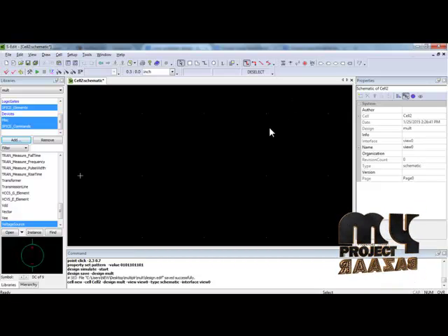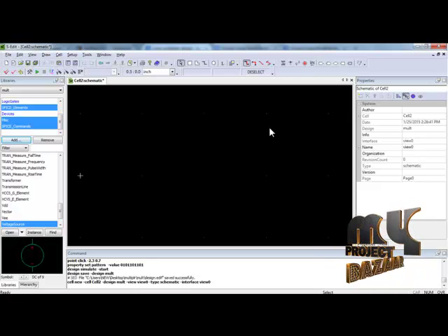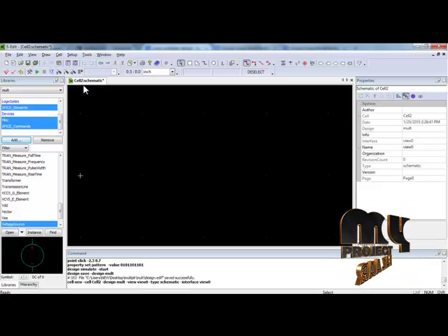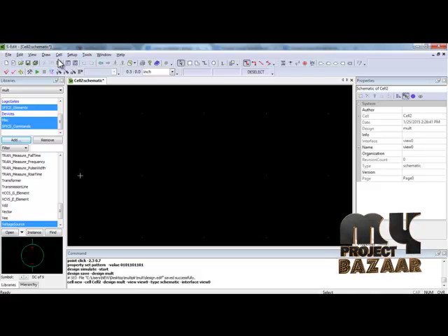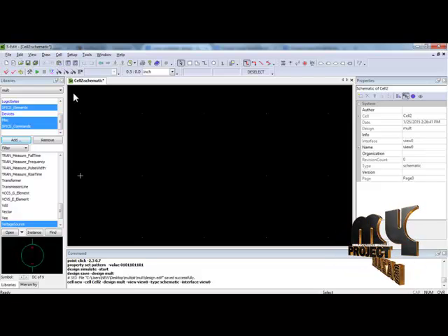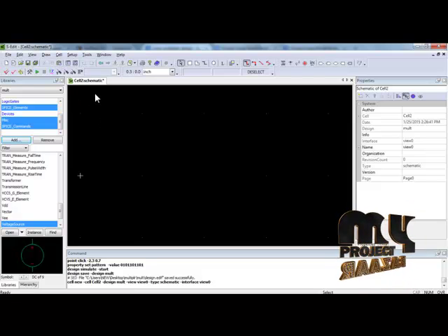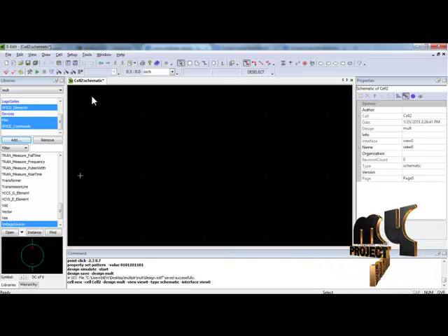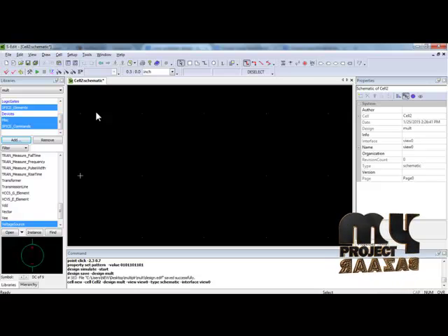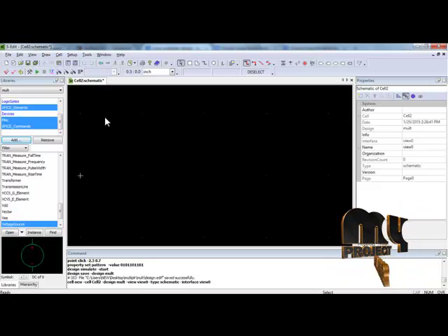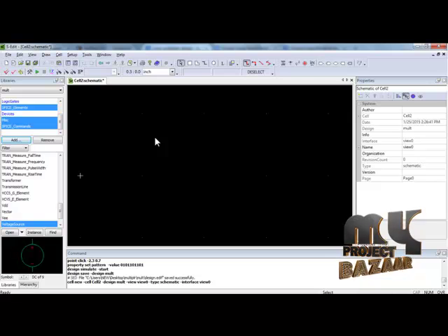So, we can design the circuit based on CMOS transistors by using S-Edit. Here, before we start the simulation, we have to select a new cell. Here is the cell menu. We have to select the cell menu and then select new cell. There you can select a number of cells like cell 0, cell 1, up to cell n. Each cell should contain a different CMOS design.